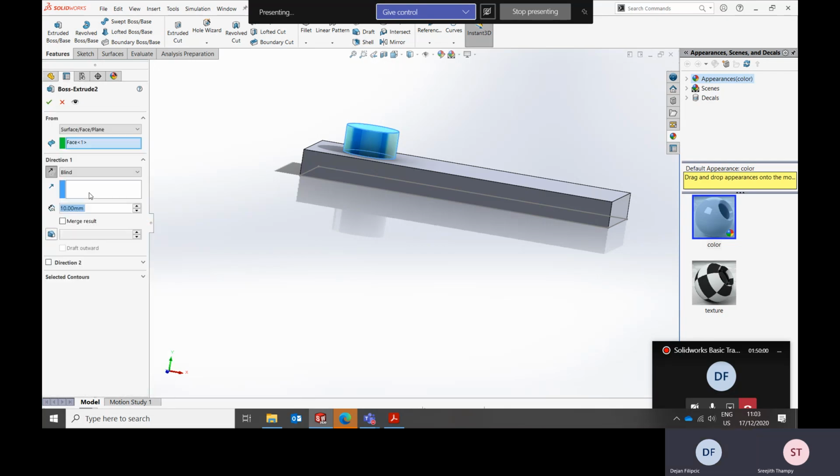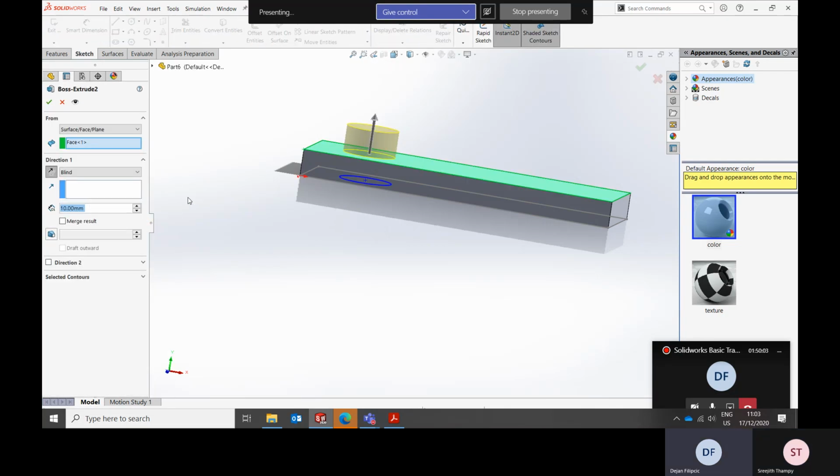And again, that's an important part that's linked to this. So one part can include more bodies than one. And when you extrude the parts in space, you can dictate to the software whether you want to merge the bodies or not. Where that is useful is that sometimes you can use Boolean functions as well, which means add, intersect, remove, and that sort of stuff. So you can create multiple bodies and then play with those to achieve a certain result, because sometimes it may be easier to have a secondary body that intersects your body to get the result you want, right?